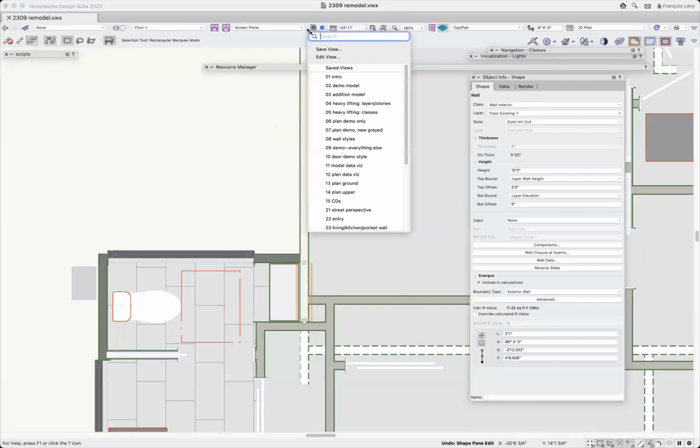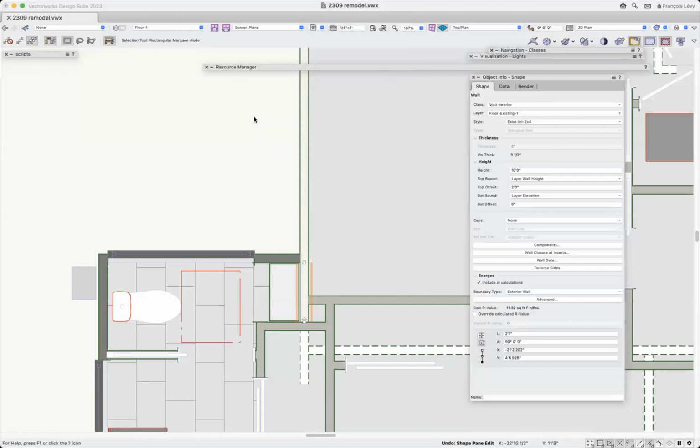So first of all, when I do this, I have pretty much like what you do, except I make a distinction between walls and partitions, and that walls are those which support ceiling joists, and partitions run parallel with ceiling joists. And the distinction is so they can see immediately, like, uh-oh, we remove a wall, we have to deal with it supporting the ceiling. And so just removing a partition, nobody cares. Right. Yeah. So the contractors have found that helpful. That's a great tip. Thanks, Bill.